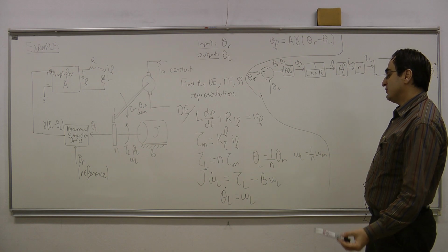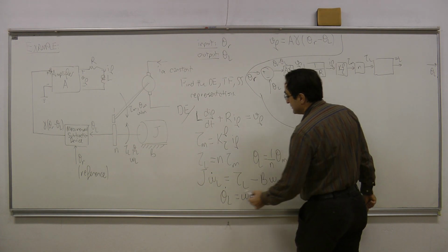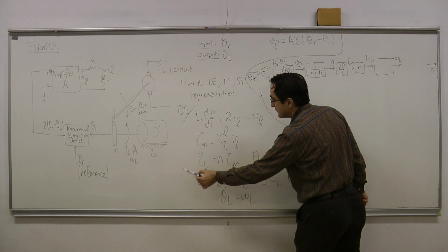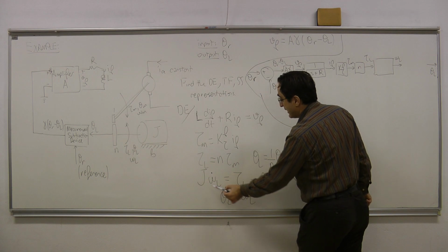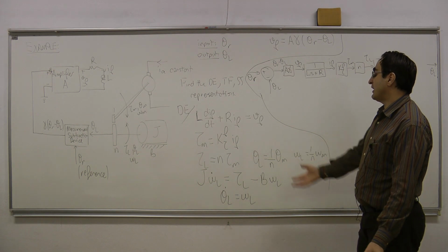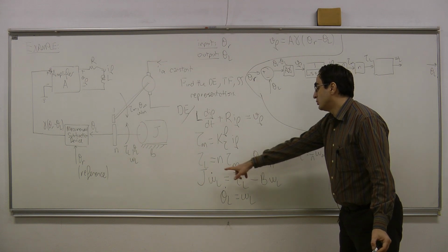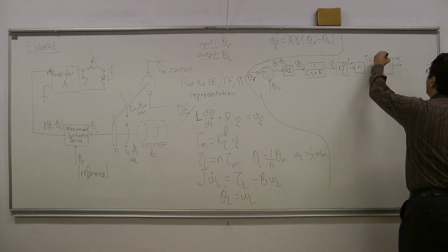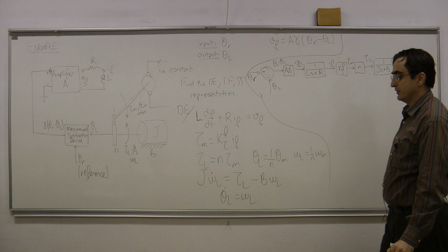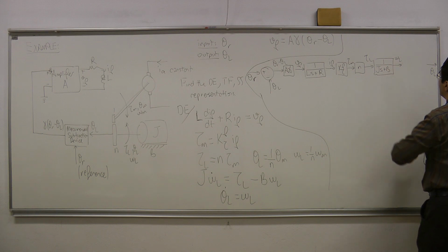If you try to do that, you will see that this is going to be Js times omega L plus B times omega L. So I have here on the left Js plus B times capital omega L is equal to capital tau L. So if I extract omega L from there, I would get omega L equals tau L over Js plus B. So I would have here 1 over Js plus B as the missing system. That is the transfer function between tau L and omega L.